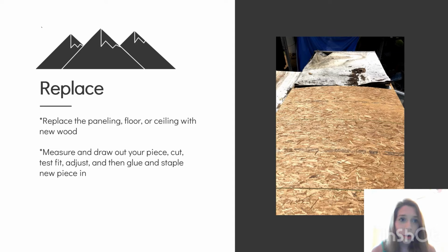Basically measure and draw out your piece, cut it, test fit it, and then use construction adhesive to glue the wood onto the frame, and then you can use staples or screws to secure it.